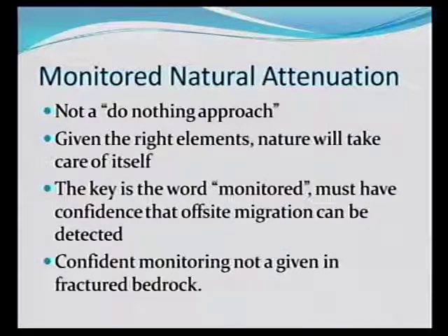Monitored natural attenuation. This always makes people nervous because they think people are walking away and saying, oh, you're not going to do anything, you're just going to leave it in there. But it's not a do-nothing approach. The key in this technology is monitored. You have to be able to assure yourself that the plume is not going anywhere, that the plume is beginning to degrade on its own, that the natural fauna are beginning to degrade the plume. And if it's happening on its own and you can assure yourself that it's not going anywhere, why not just sit there and watch it go away?